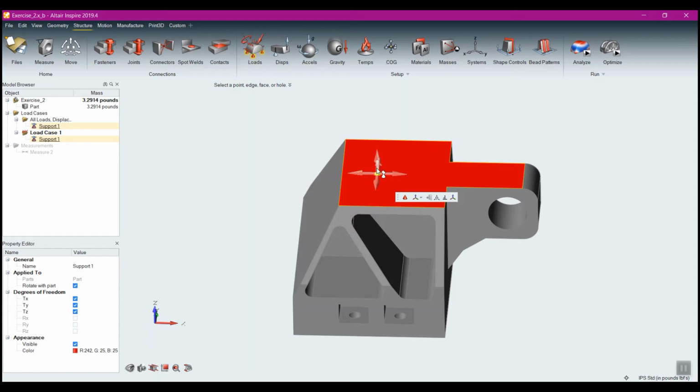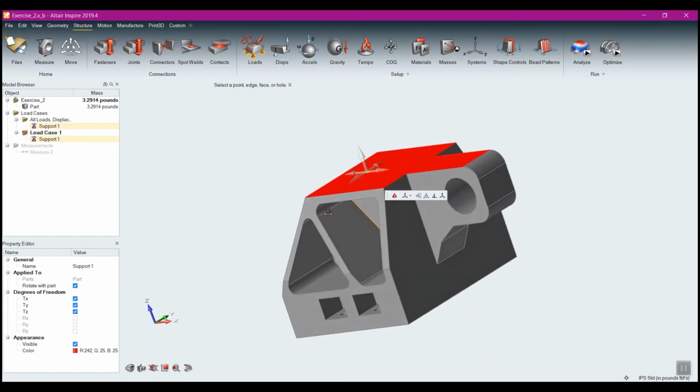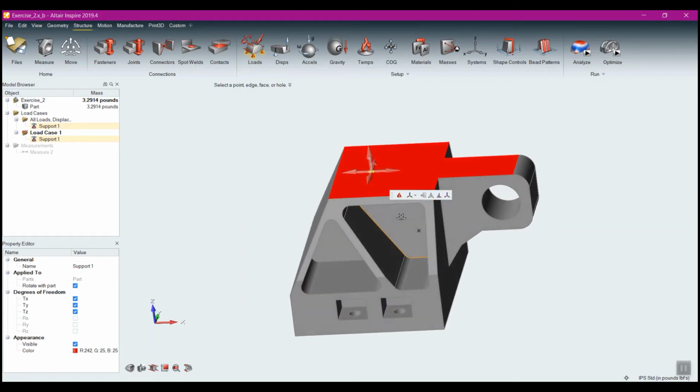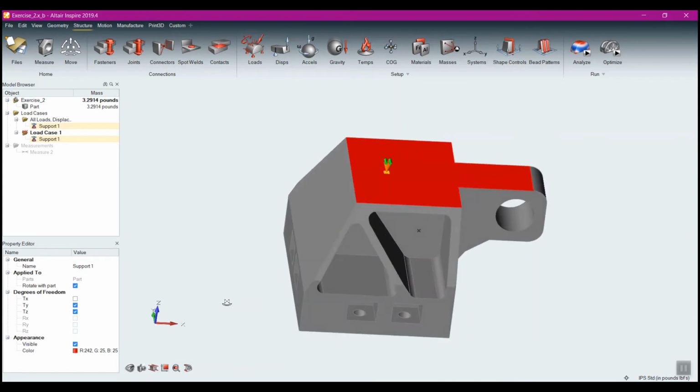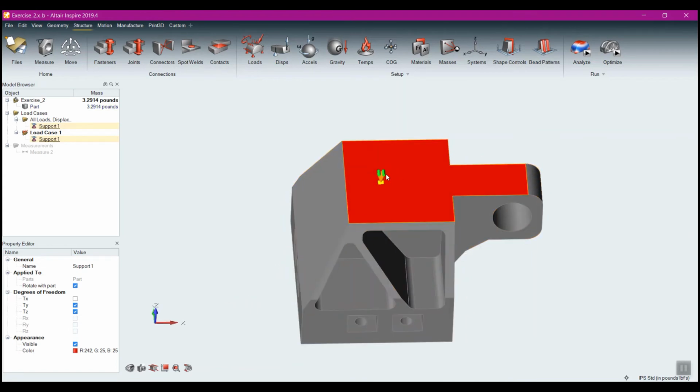So I can just double click on that. And now you'll see I get these little pointers here. If I select one of them, it turns green. And now when I right click to get out of this edit, my icon has modified to include these roller wheels. The roller wheels will show me the direction that it is now free to move. So it is now free to move in what amounts to, what's that? Looks like the x-axis there. So now free to move in the x-axis.